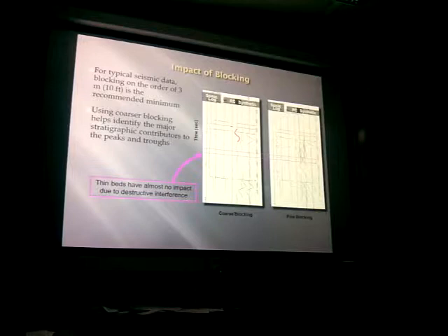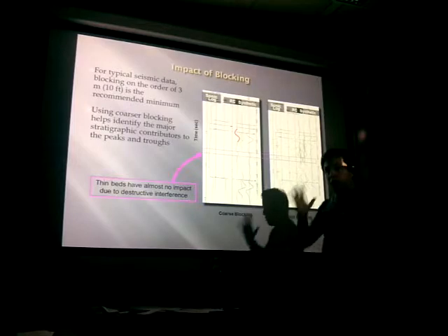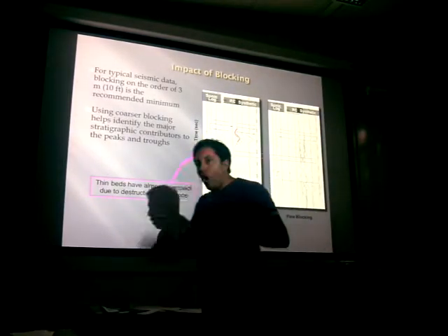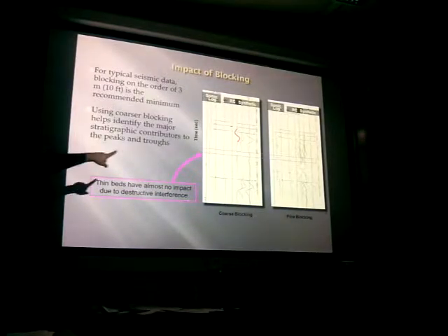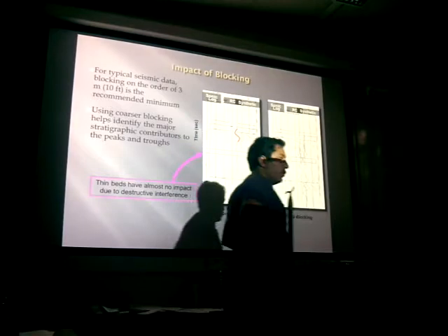It's not easy. And that one is going to be different from that one. It's going to be different from that one. Slightly, but it's going to be different. So that is the stage when you are doing your well-log calibration. I literally think this is the most delicate step: the blocking, choosing the windowing, sampling of your sonic well-log that you upload in your seismic dataset, because it's going to affect terribly the way you produce the final synthetics during the convolution.